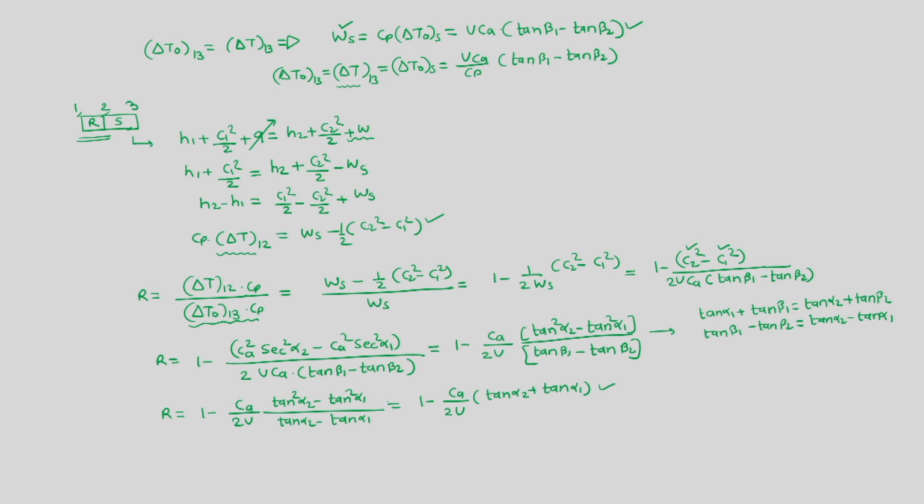This formula can further be utilized to understand how the R is going to vary with respect to the blade height. So, here we know that our formula for degree of reaction is this, and here we have Ca tan alpha 2 and Ca tan alpha 1. Okay. We will do it after one more derivation, which is called the free vortex theory.